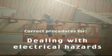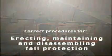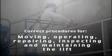Training should include the nature of any lift hazards, electrical hazards, fall hazards and falling object hazards in the work area, the correct procedures for dealing with electrical hazards and for erecting, maintaining, and disassembling the fall protection systems and falling object protection systems being used, the correct procedures for moving, operating, repairing, inspecting, and maintaining the type of lift in question, proper use of the lift and proper handling of the materials on the lift, the maximum intended load and the load carrying capacity of the lift used, and any additional requirements set by the manufacturer.